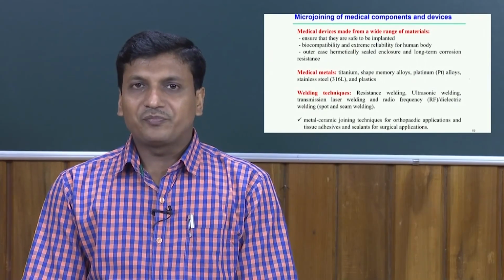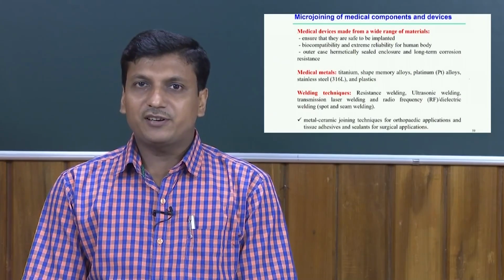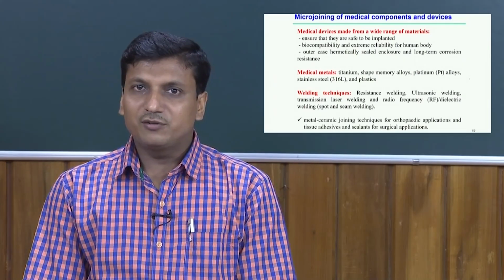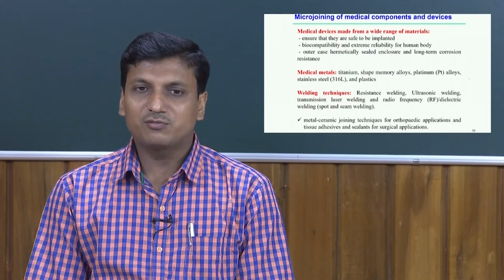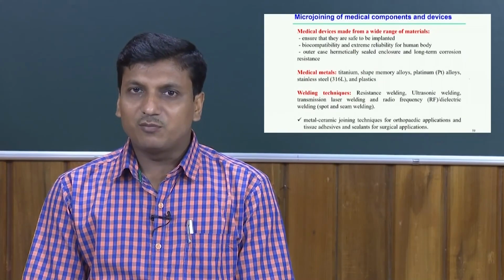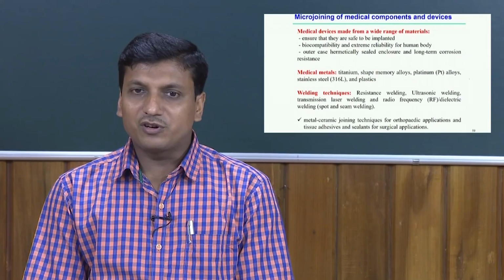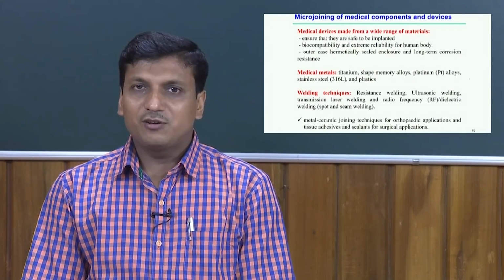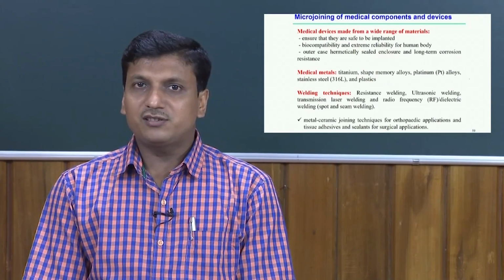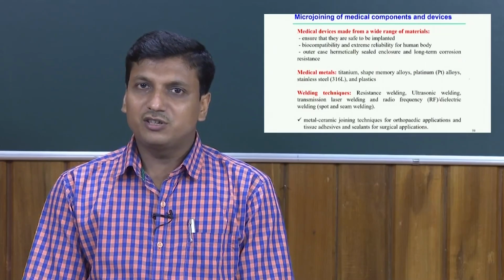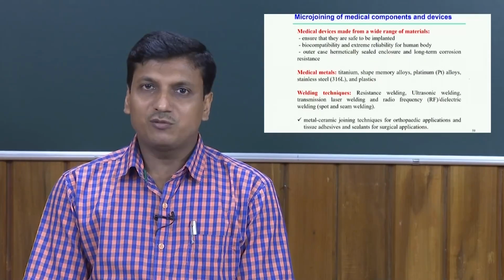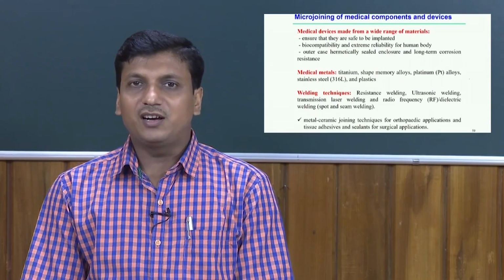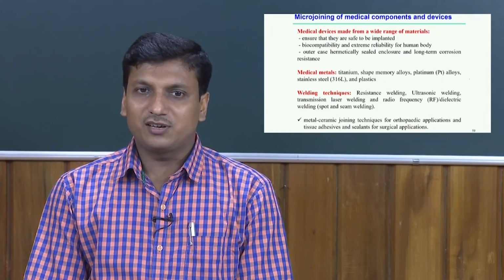For example, it should be least affected by the surrounding materials when we choose certain joining or welding technologies for medical components. That is the most important requirement. So very precise control of the heat source may be required, and in that respect laser welding techniques are generally more suitable.